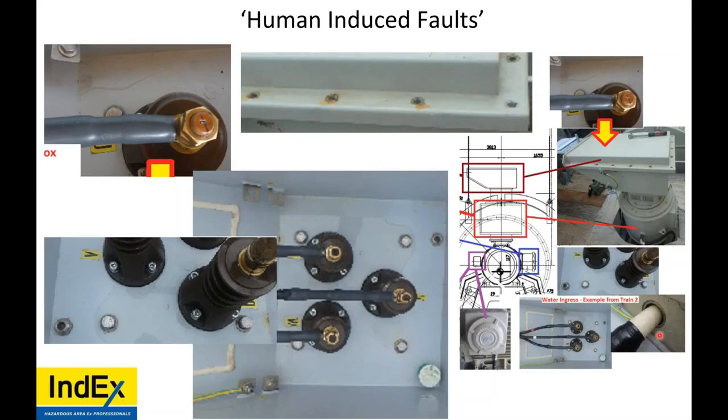Now, water being in a gaseous or vaporous form, got in and got onto everything internally. The competency of the people indicated that a small little breather drain and a small decondensating pack would be enough. Obviously, in this instance, when we're dealing with high voltage, this is not sufficient.